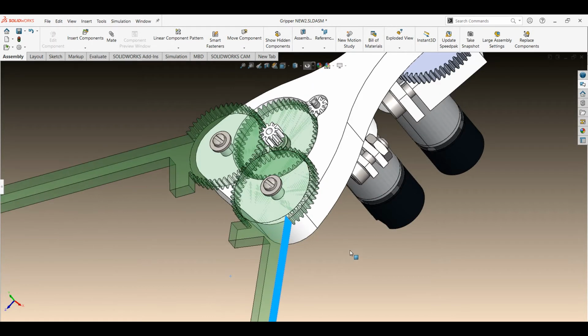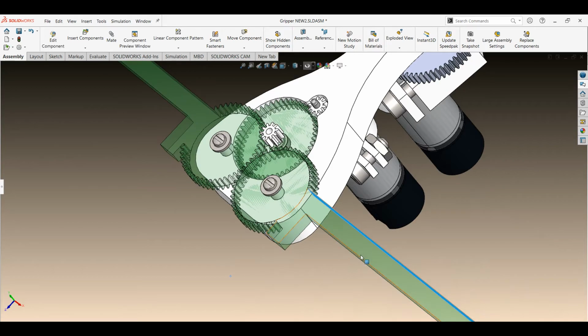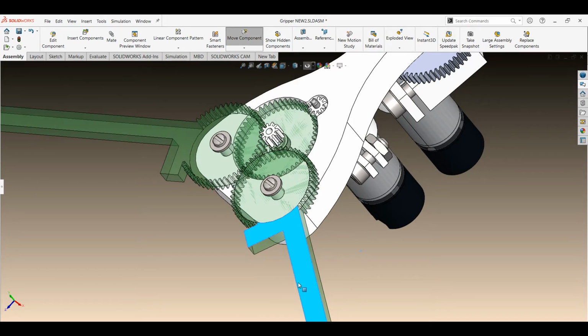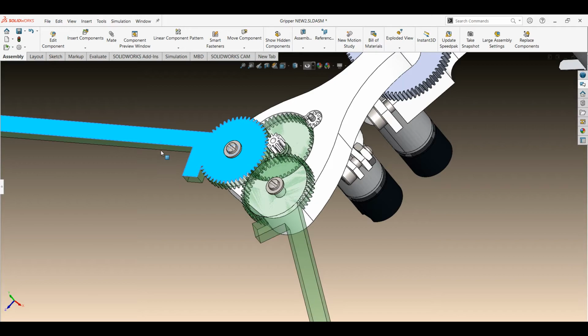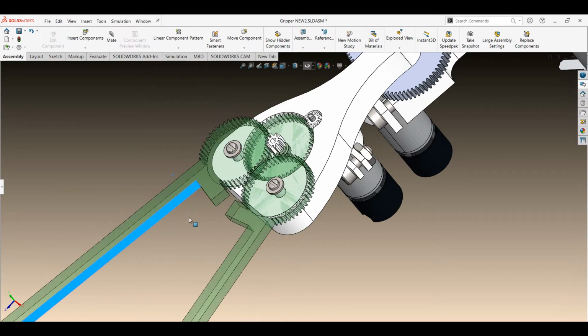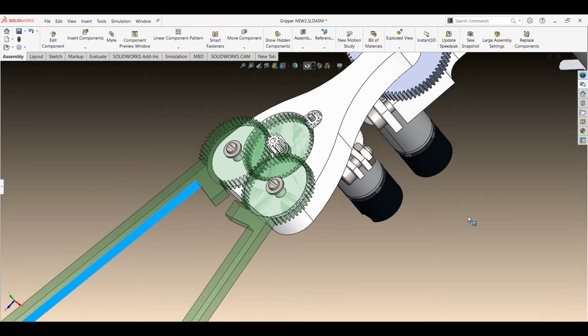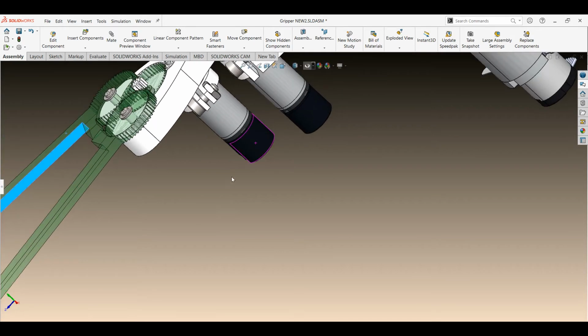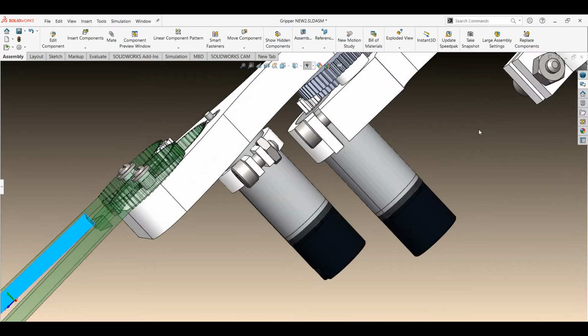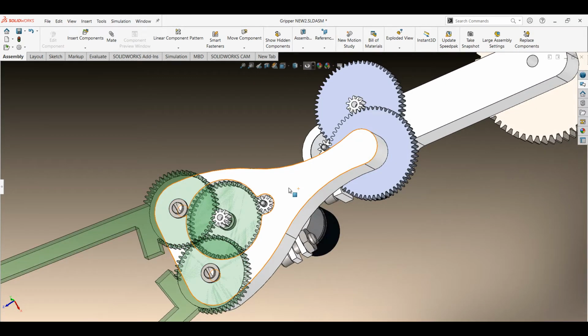Here we look inside the gears. We have a ball bearing inside the lower gear to reduce friction. Additionally, the pincers are being secured with a screw. In between the screw and the gear is a standoff, and to reduce friction, washers have been added. You can see that at the bottom, the motor is secured with a clamp.